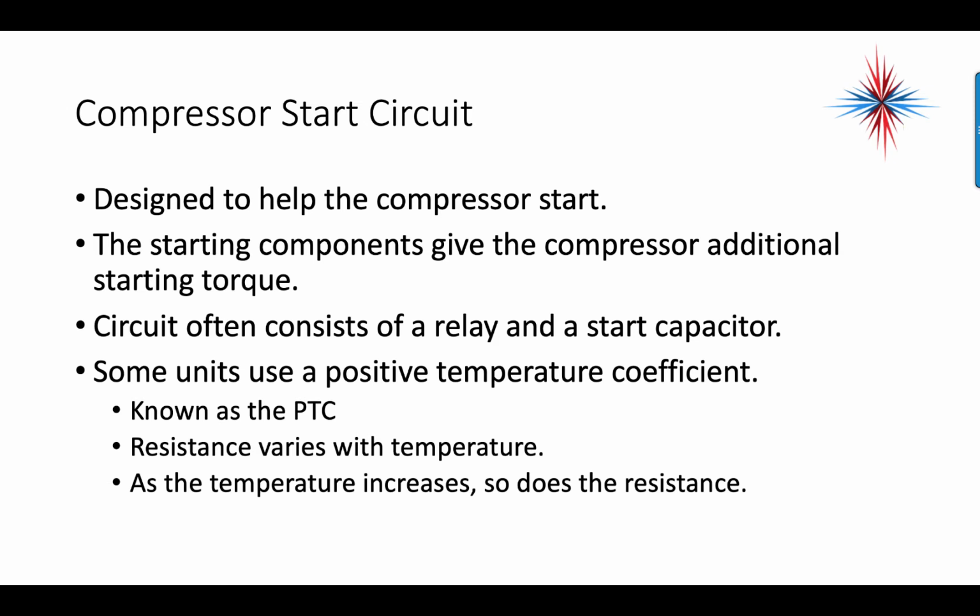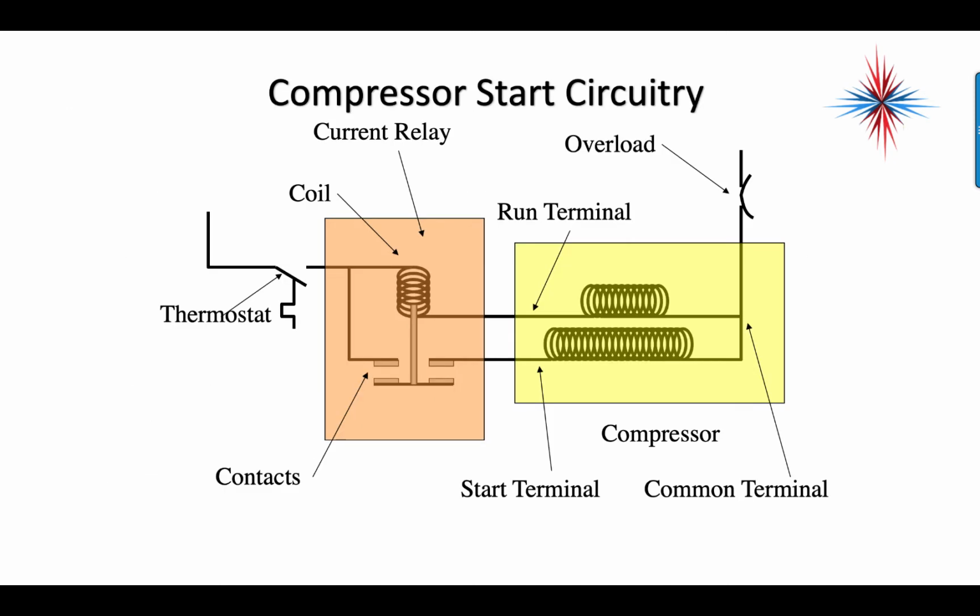So a lot of times these motors are CSIR. Okay, capacitor start induction run. Some units use a positive temperature coefficient known as a PTC start relay. The resistance varies with the temperature. As the temperature increases, so does the resistance.